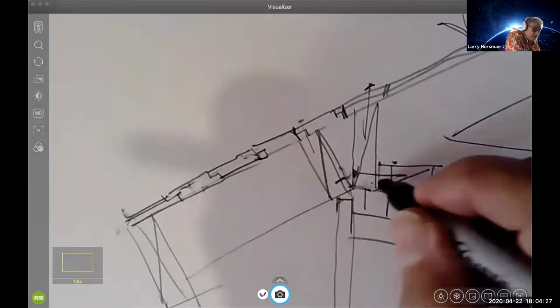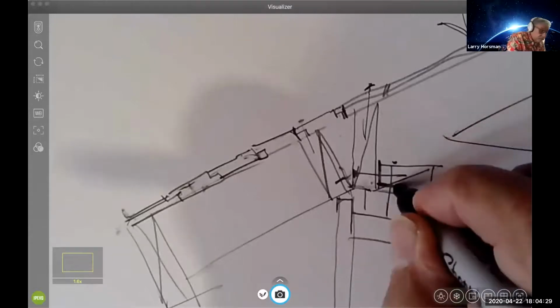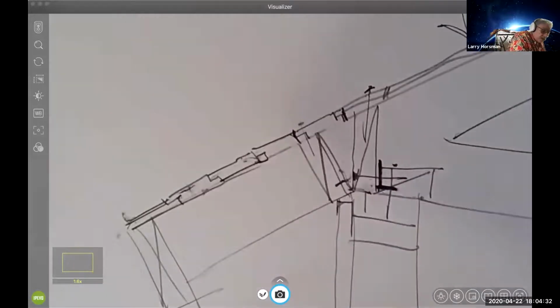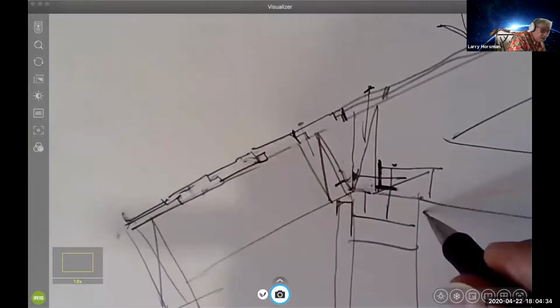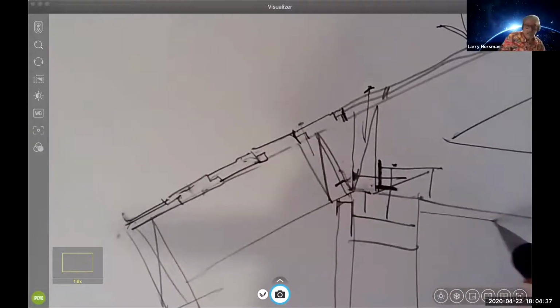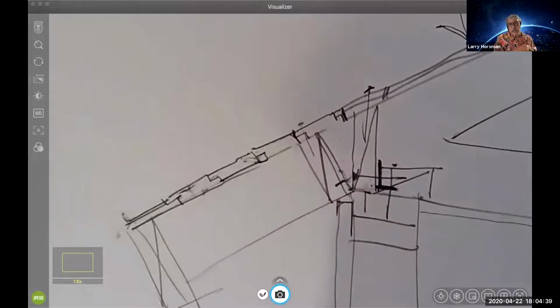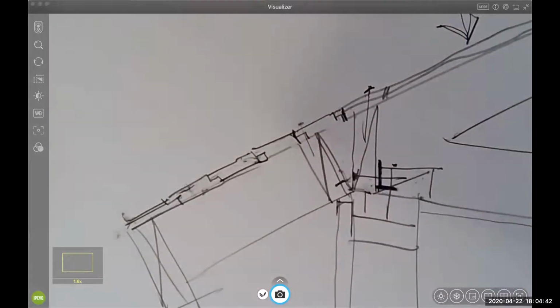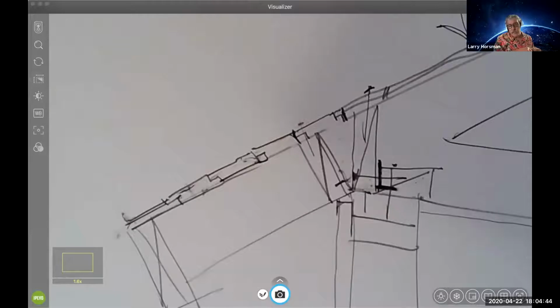The problem is if you're putting in drywall, trusses are normally at 24 inches on center, and usually you need some drywall backing for the nailing, because the perimeter nailing on the drywall is normally I think 7 inches for nails and 12 inches for screws, so you still need some backing for the drywall. You don't have to use it.